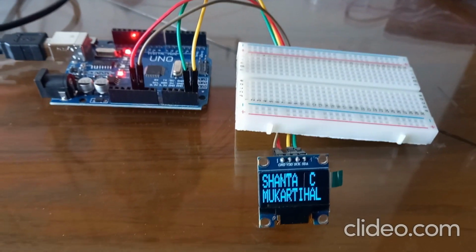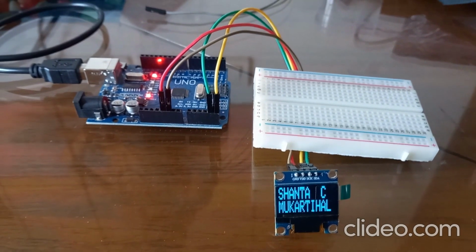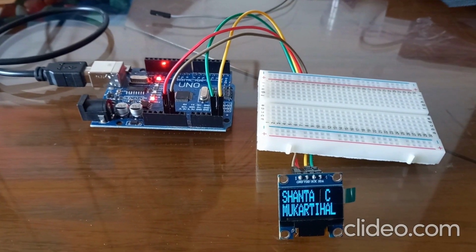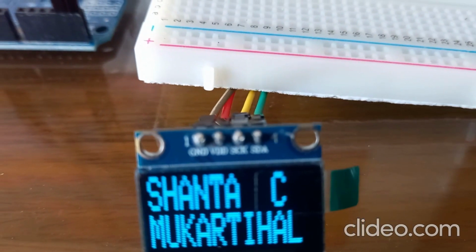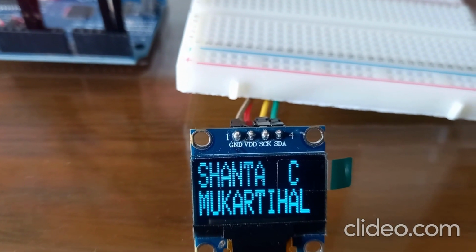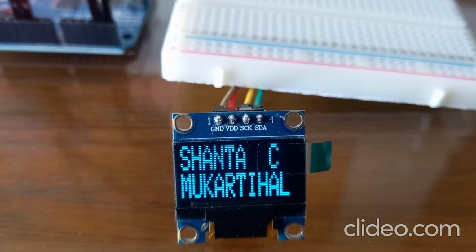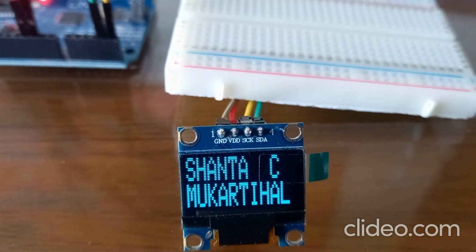This is a simple experiment to interface an OLED with Arduino Uno. And the same OLED display you can interface with NodeMCU also. It has got 4 pins: ground pin, VCC pin, SCK, which stands for serial clock, and SDA, which stands for serial data. So these 4 pins should be connected to either Arduino Uno or NodeMCU.